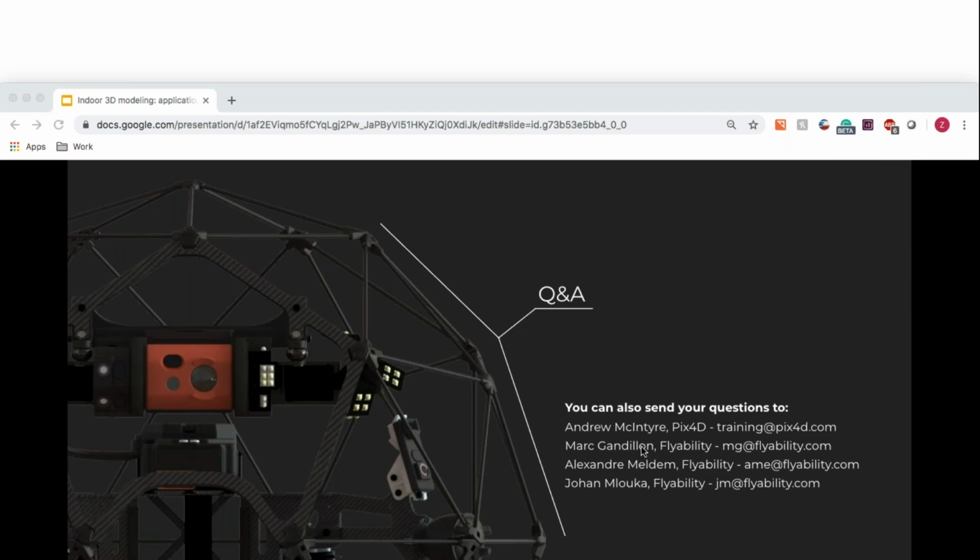You'll need to be able to identify common points between the real world reconstruction that is georeferenced in absolute space and the relative reconstruction that you've generated with ELIOS 2. And there are a couple of ways to do that. One example that I have seen in an indoor environment like a mine was they had shot ground control points using a total station, underground obviously, and they used a handful of those shots to georeference their results.